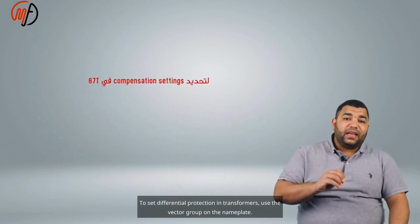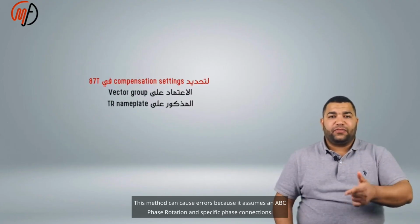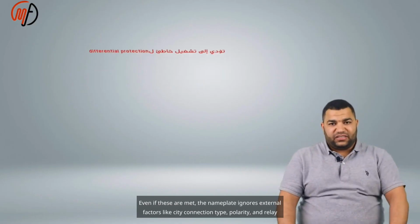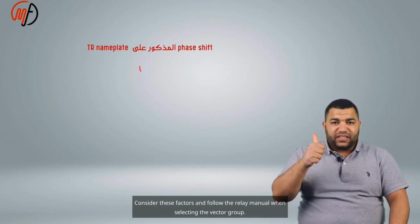To set differential protection in transformers, use the vector group on the nameplate. This method can cause errors because it assumes an ABC phase rotation and specific phase connections. Even if these are met, the nameplate ignores external factors like CT connection type, polarity, and relay input connection. Consider these factors and follow the relay manual when selecting the vector group.